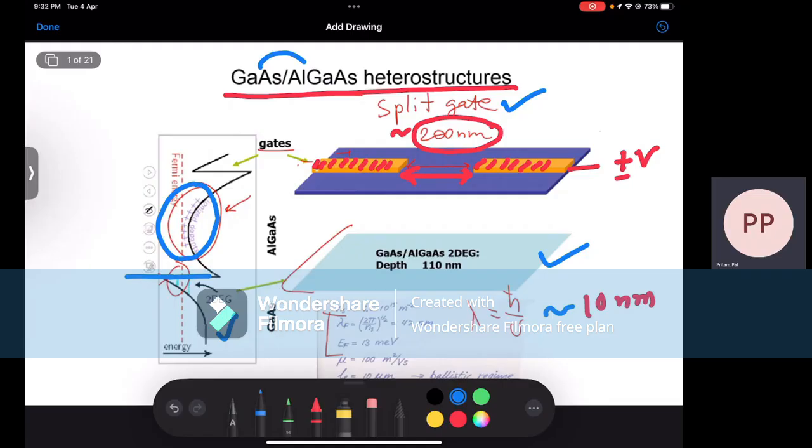And if you have a gate going all the way across, with a very negative potential on that gate, you can separate the 2DEG into two parts, in front of the gate and behind the gate, and those two regions will be unconnected because in between there will be a region depleted of electrons. Think of a p-n junction diode, right? Remember, there is a depletion region in between. This is what you can get with a gate in the 2DEG.